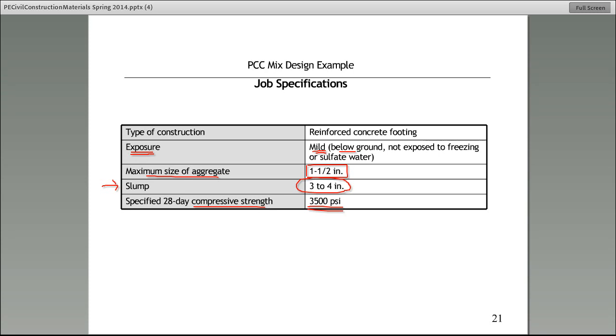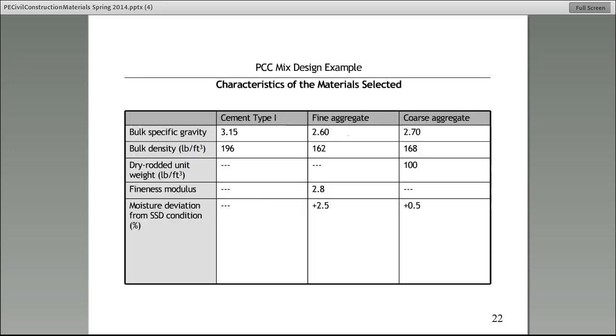All right? But remember, this 3,500 psi is what Joe in El Paso or Elizabeth use in their actual structural design. All right? And we need to convert this to what we called f'c required with those equations that I showed you.